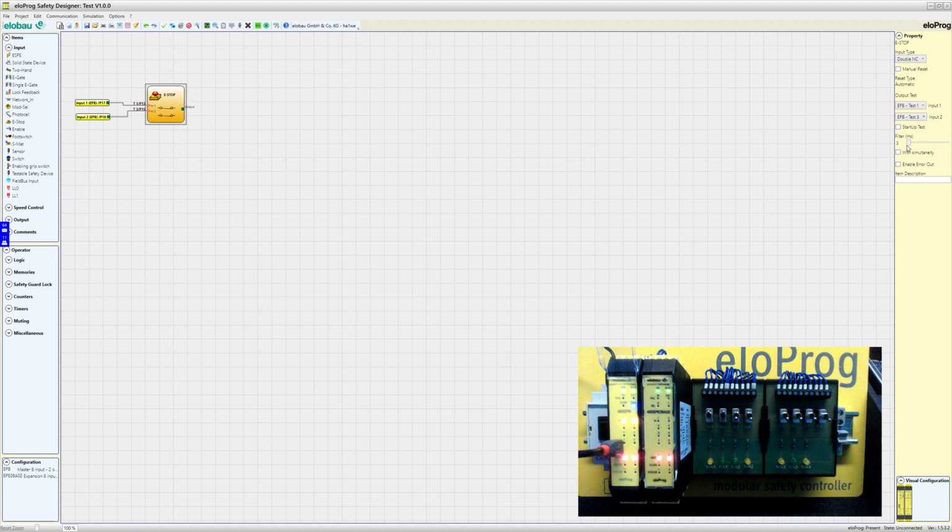So, and we have a filter. The filter is very important for such mechanical devices which can bounce. This is a filter to reduce the bouncing, or in that time you choose here, the bouncing is ignored, and so you can always have a small amount of filter time which reduces the bouncing.